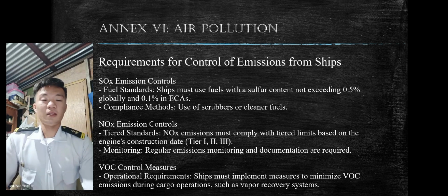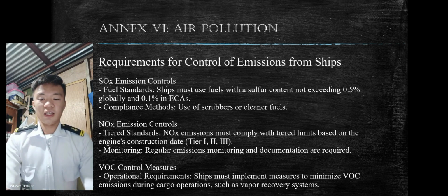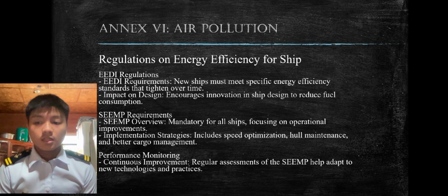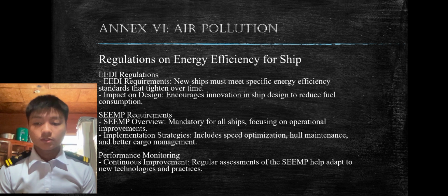In Regulation 7, ship waste, particularly equipment containing ODS, when removed from the ship, and exhaust cleaning system residues, must be properly discharged to a reception facility. Regulations on energy efficiency for ships. EEDI regulations. EEDI requirements: new ships must meet specific energy efficiency standards that tighten over time. Impact on design: encourage innovations in ship designs to reduce fuel consumption.